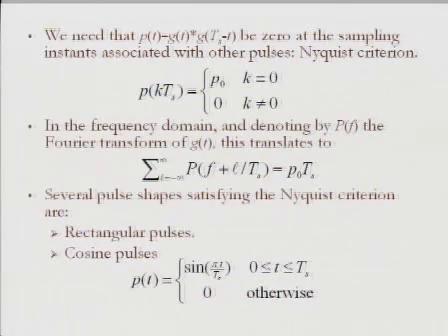Okay, so first of all, how do we sample a signal? Okay, we have P of T, and we want to sample it every capital T sub S. How do we sample a signal? You guys not seen this before? Can you multiply by something, for example, to get a sampled version? Exactly, impulses. So what we want to do is we want to multiply it by a train of impulses spaced by T sub S. Very good. So we want to take P of T,